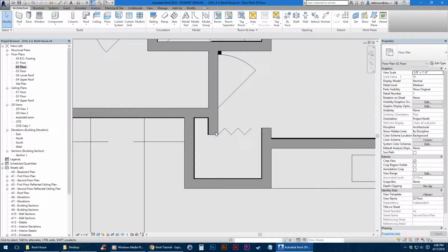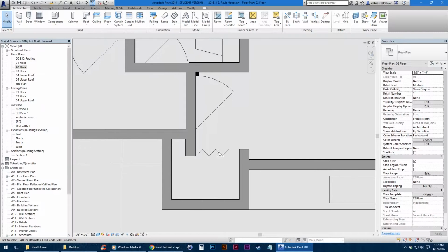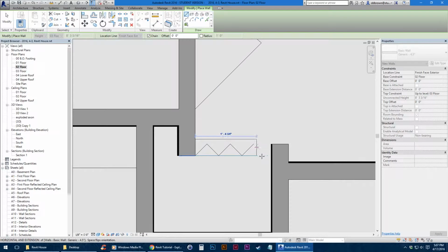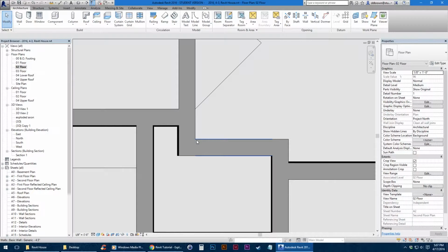So in this part of the drawing, you can see that we have a door here, and then there's also a folding door here. Now I haven't drawn any wall in here, so I'm not going to be able to actually put a door in. So I'm going to have to go in with my wall tool and then place a wall. Even though the door can be, like, say, the width from all the way from here to here, there still needs to be a wall there.